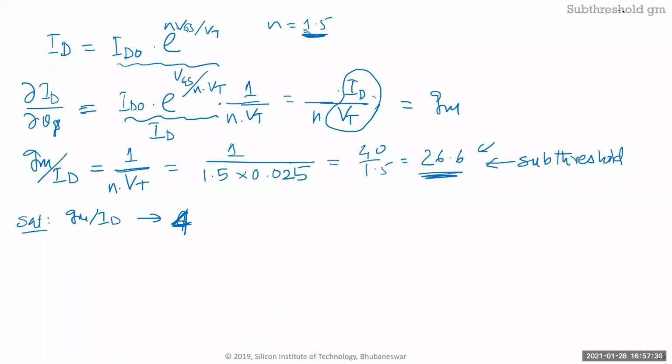Like I was designing the amplifier. So we'll go back to that amplifier and see how to change the GM over ID. Less ID, more GM, right? So basically, I'm getting the same amount of GM with 4 times less current, which means that if I'm designing an amplifier, it's usually GM times, if you remember that equation we had, 2 over lambda over VGS minus VT, or we said V effective. I can write this as 2ID times ID times lambda times V effective.